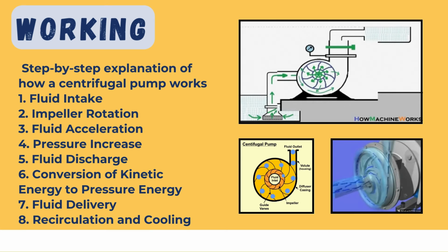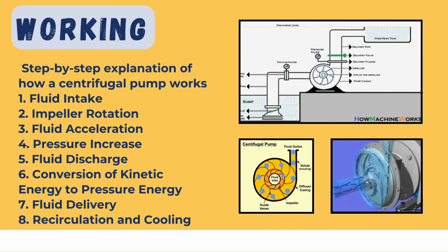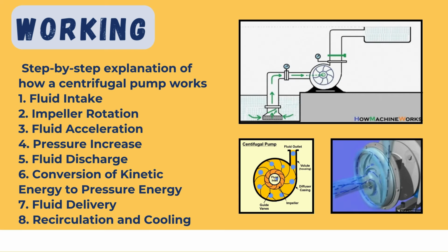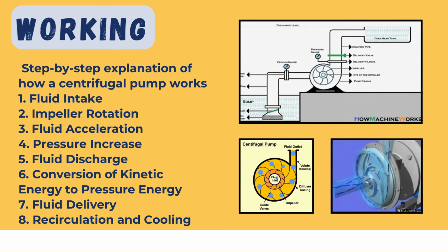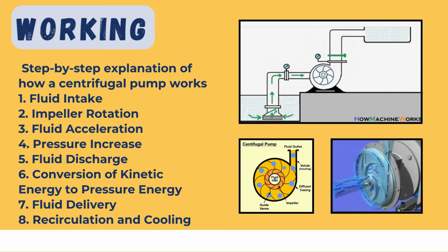And guys, here also comes the conversion of kinetic energy to pressure energy. As the fluid enters the volute, the gradual expansion of the casing converts some of the kinetic energy of the fluid into pressure energy. This leads to an increase in the pressure within the pump, enabling the fluid to be pumped to the desired location. So guys, at this stage, the fluid has gained proper energy and the pump is also pressurized. Now it is the proper time for the delivery of the fluid.